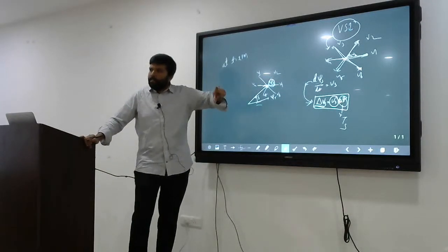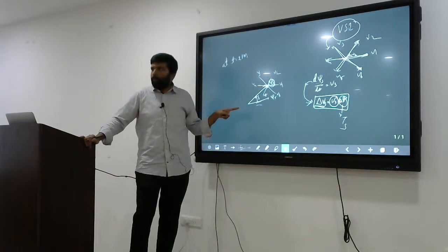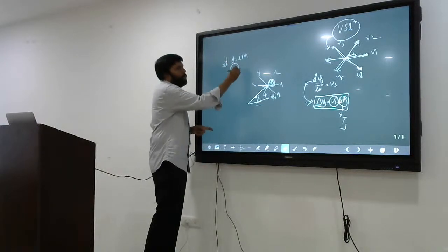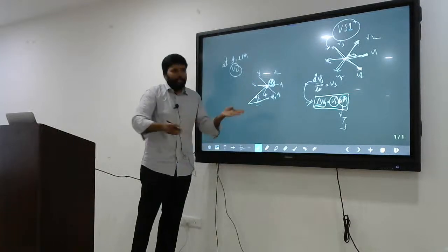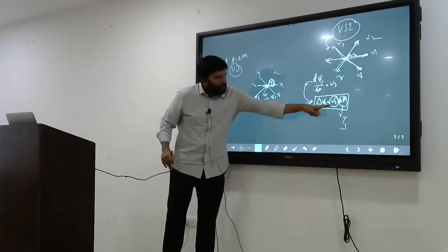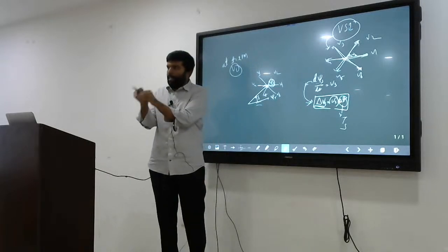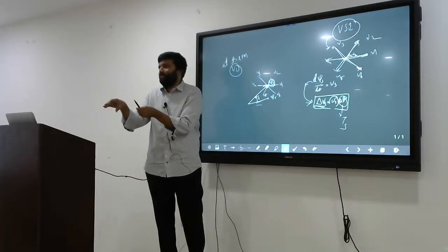At the next sample instant, at exact t equal to 2 pm, if you apply the V2 vector, what will happen? V2 is nothing but a voltage. If you add some voltage for a particular time, flux will also add.